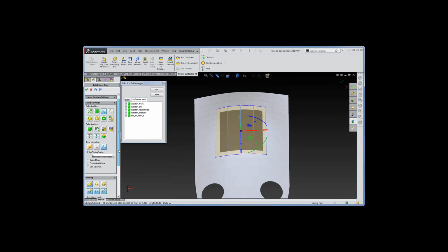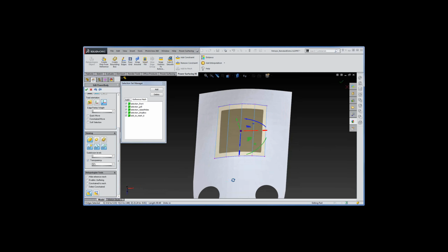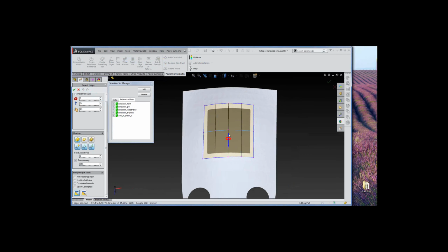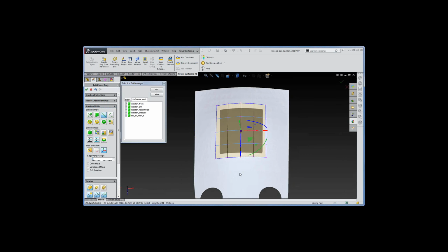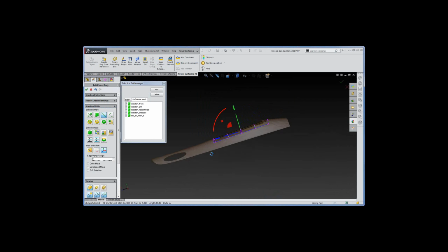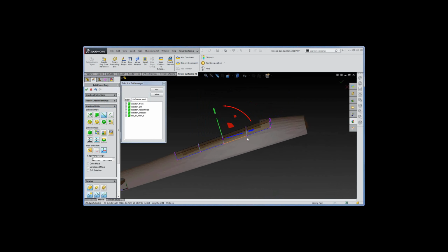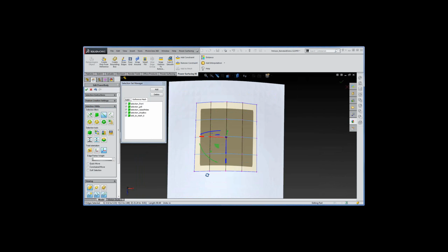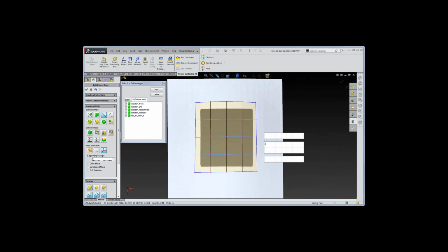And the nice thing is that we can leave these as constrained to the surface, and that's what the magenta color tells us. But we can also uncheck constrain the mesh. So that's kind of a constrain the mesh mode. So now I can go in and I can add my edges, right-click. And as you can see, everything was kind of straight. It still doesn't do too well as far as that surface goes, but it's the beginning of what we're going to do here. So now I can go ahead and subdivide it,